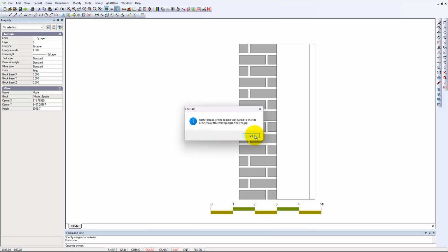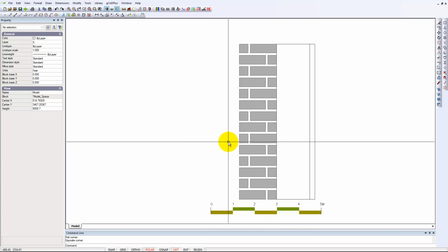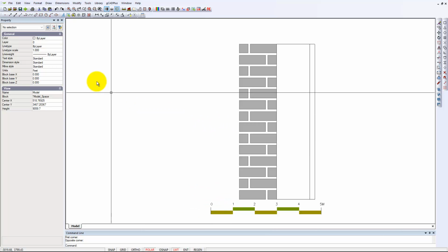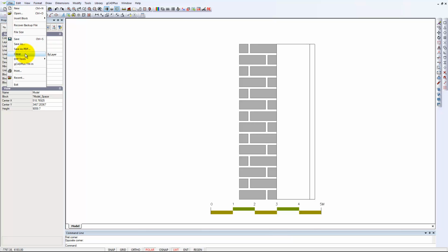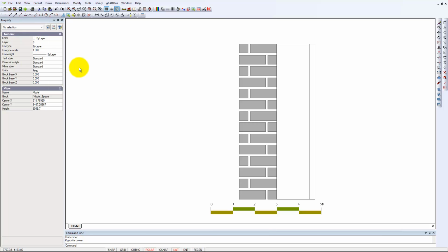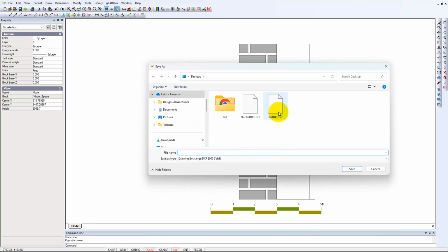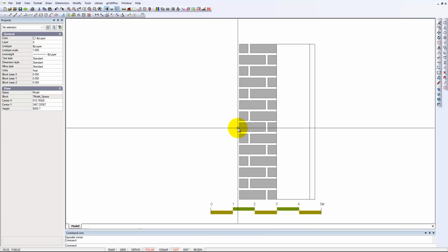And it's been saved now to the desktop, so we can import that into SketchUp and scale it and build our model on this image. And alternatively, we can say File, DXF Tools, DXF Out, and we'll try going our DXF out. I've rehearsed it. So now we have the two types of files ready for the next stage in SketchUp.